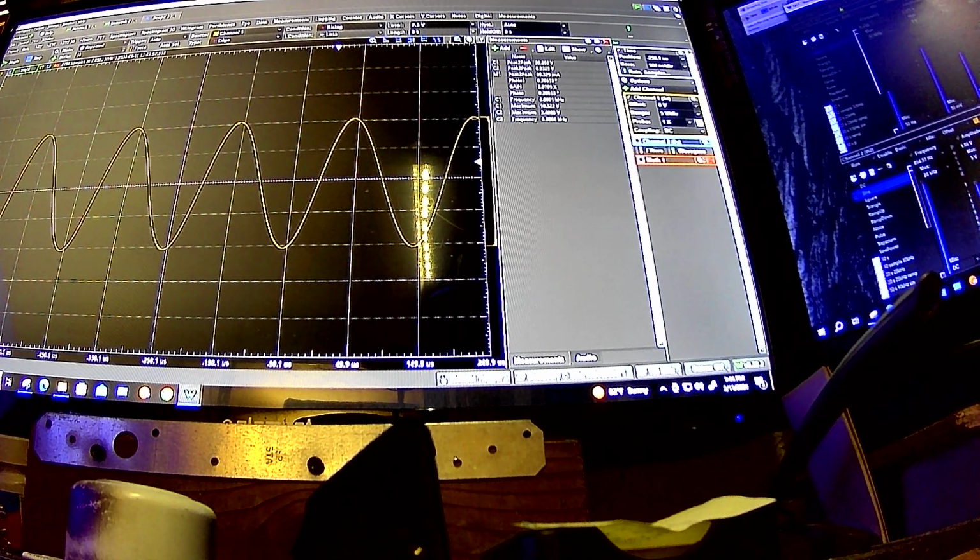But the fact of the matter is, if I shrink the signal size, you eventually start running out of resolution, because this thing will only put out a maximum of 5 volts divided by, say, 4096. So it's limited to about 1.2 millivolts per step, theoretically. If it's 14-bit, it'd be less than that. And I think it is 14-bit because you can get down to